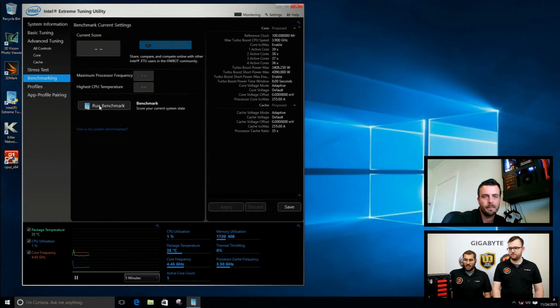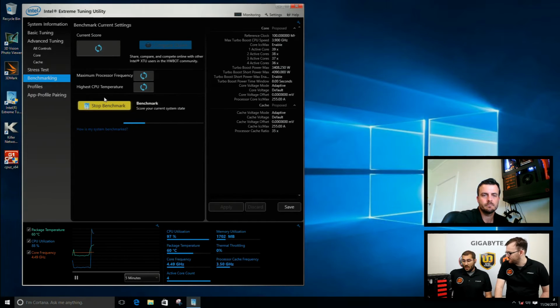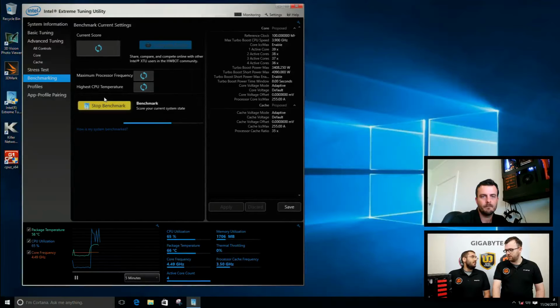Okay. So I will start XTU running. As before, you can actually see the actual CPU frequency down here. And I notice we also have a higher temperature. Of course, when you overclock your CPU and you raise your CPU voltage, you get higher temperatures. But the Skylake architecture is actually not so bad, so you won't see very high temperatures on your CPU. Right, so right now we're at about 63 degrees Celsius, and that's still a very safe temperature.